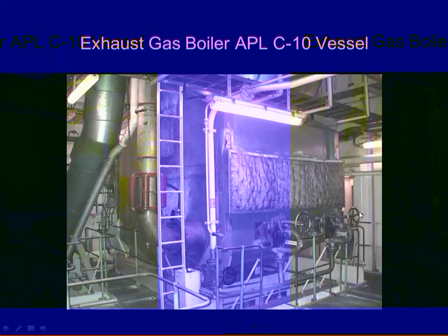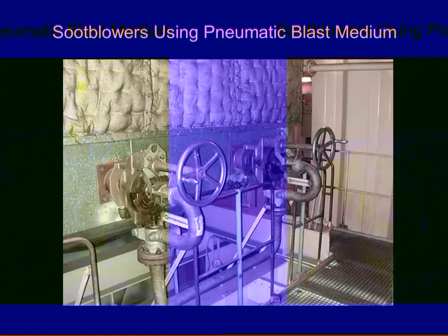By the way, on these soot blowers, on this particular engine, there was not enough heat available to run steam soot blowing. There's not enough steam production, so they actually use start air as the medium instead of steam. So that's a closer look. And again, if in doubt, blow tubes. Keep them clean.